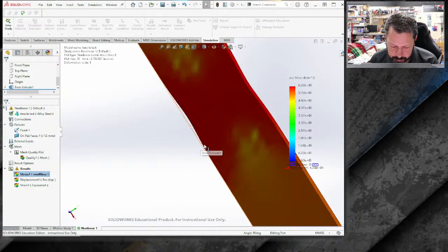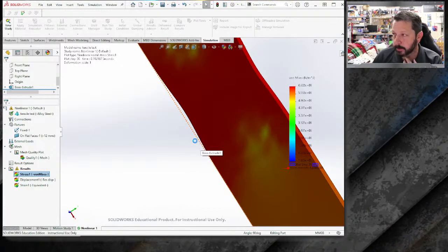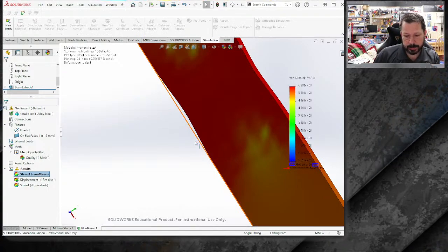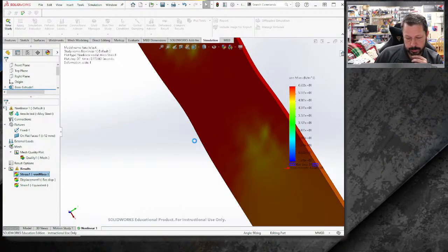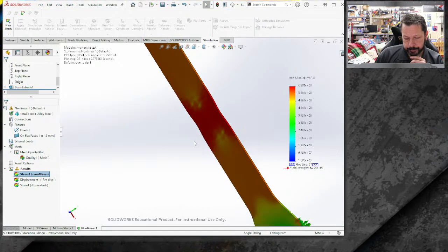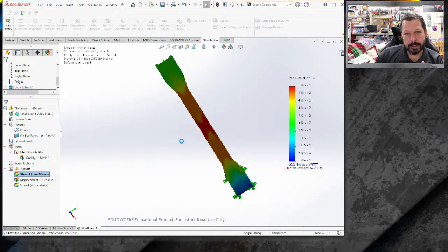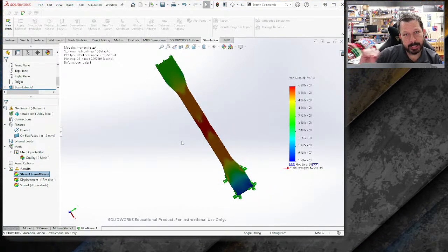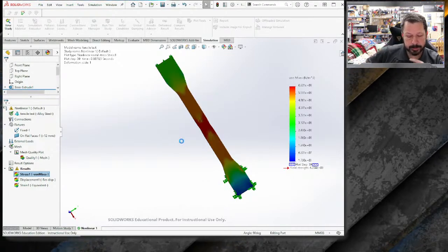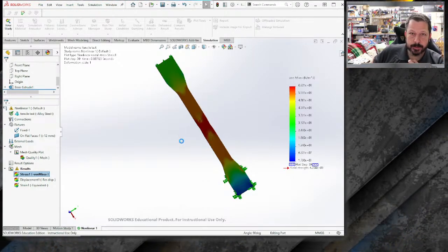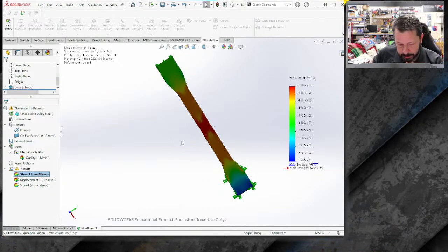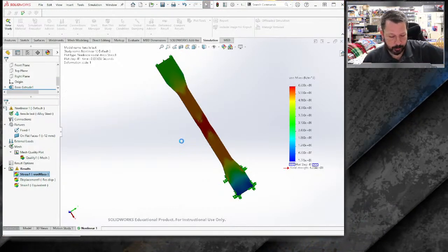But you can definitely see the neck is forming right there now. You can see how far it is. That dotted orange line is the original shape, and you can definitely see there's a neck forming in there. That's also why we needed to select a material that had that plasticity option, so that it can actually do this. Otherwise, it would just calculate the stresses, and it wouldn't necessarily show this neck forming.